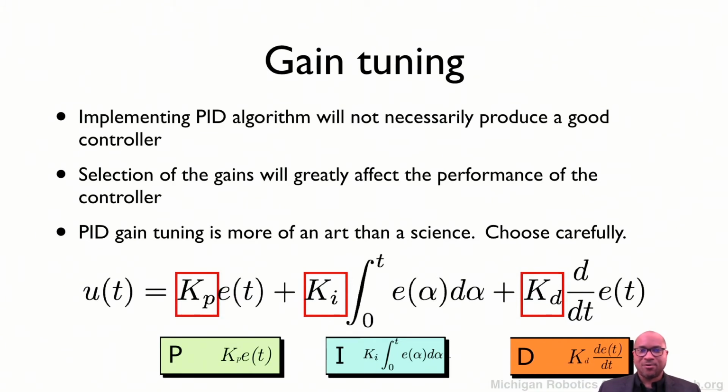But also, encoded in this is the dynamics of our system, right? This PID controller knows nothing about what's going on in the actual dynamics of the system. But yet it's able to produce this control by minimizing error. And so implicitly, these gains are defining what is actually going on in the dynamics of your system.